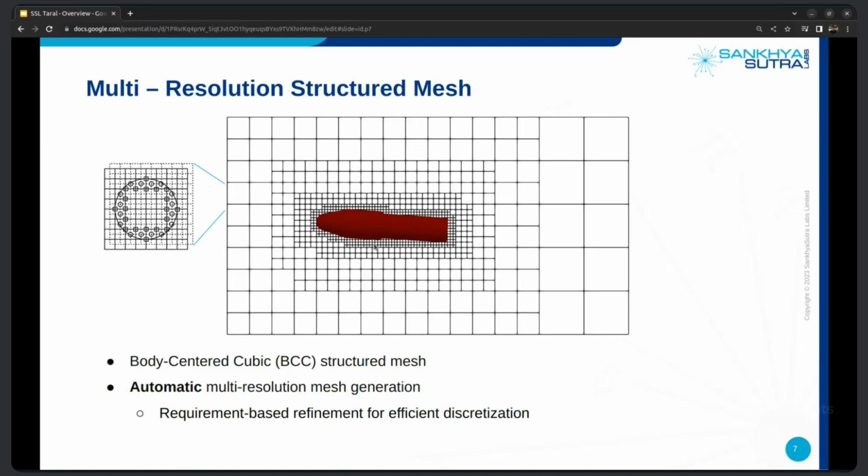And what you're seeing here is not the cell size, but the interface of blocks. A block is a collection of cells, which is the unit measure for what we transport to our processor. So each block is taken by one processor when you submit it on a multi-processor environment. Each block has 24 cells in each direction. So the actual grid that you're seeing here is not the full representation of your cell sizes.